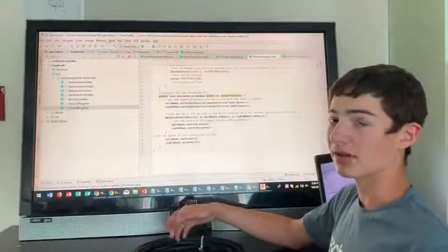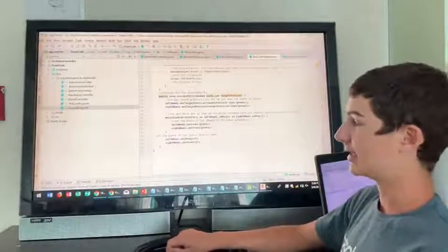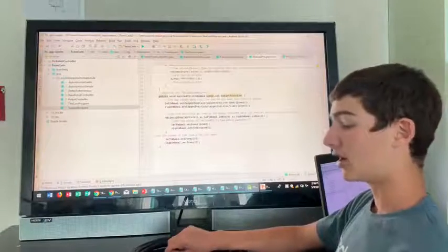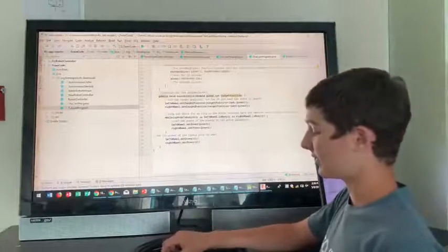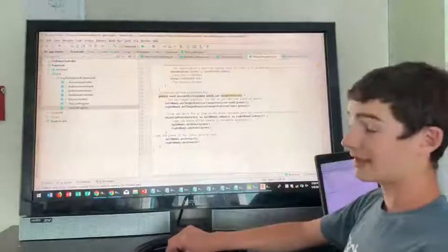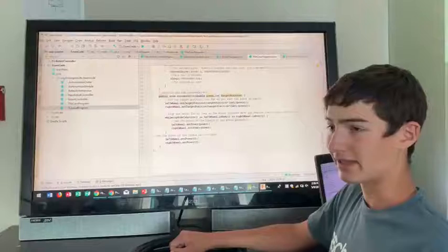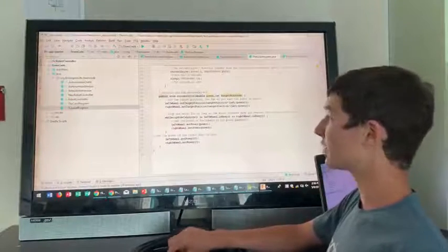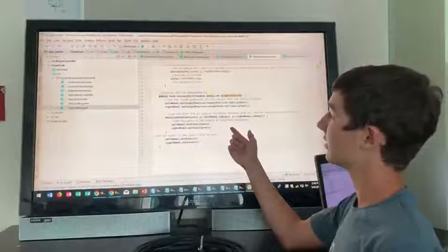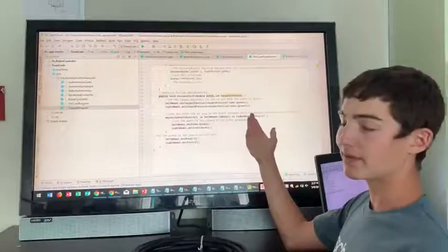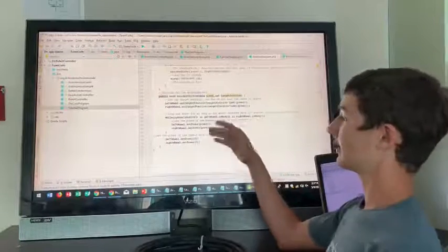You also have to make sure that your hardware is done perfectly before you can even start programming, because if the hardware is not done right, the robot's not going to respond. And that is a frequent problem. Encoders can be very difficult to program with, but the wiring of them has to be done carefully as well. So before starting, make sure that the encoders are set up properly. Generally, there are quite a few ticks in a rotation. So estimating it, there's some amount of ticks.